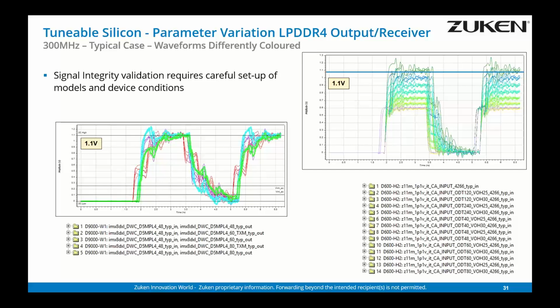These different models on driver and receiver side show a completely different behavior. Here we see this tiny little overshooting, and we see different voltage waveforms. I don't want to dive into the details of the different waveforms. Just take the message: the different models and different settings behave differently. So choosing the proper setting can be key for success in a low power DDR4 design.